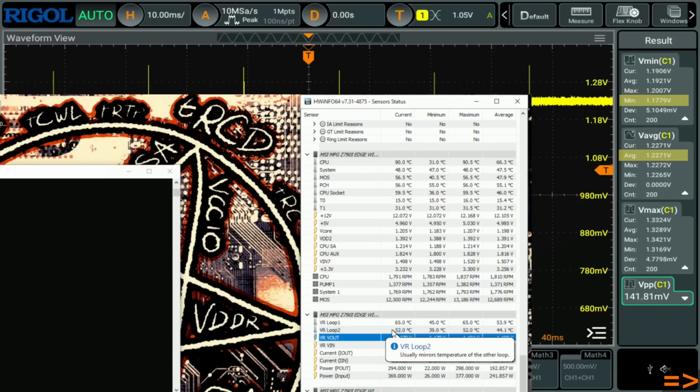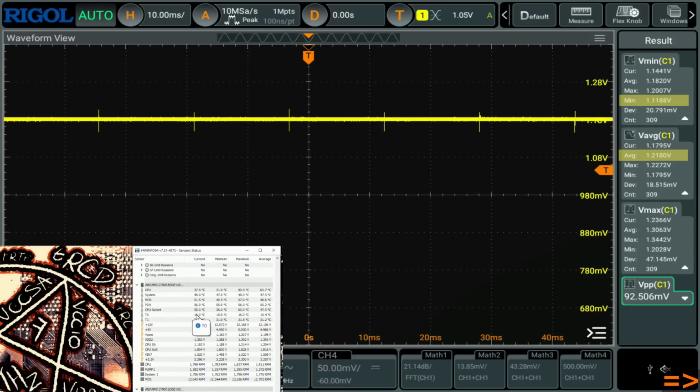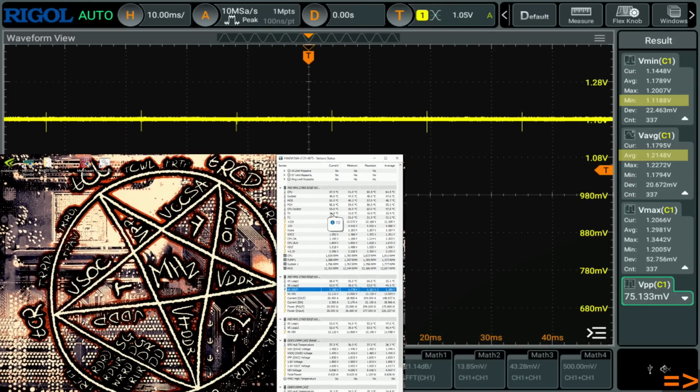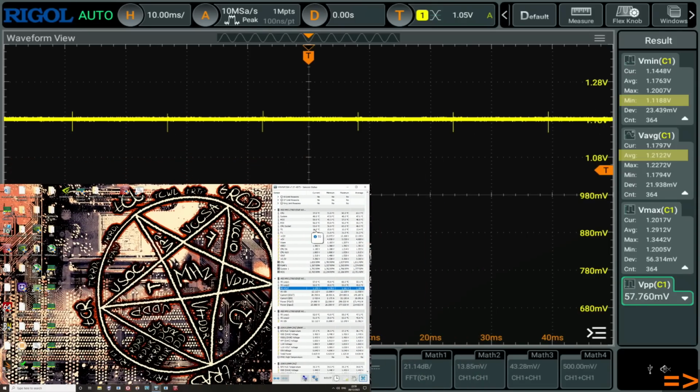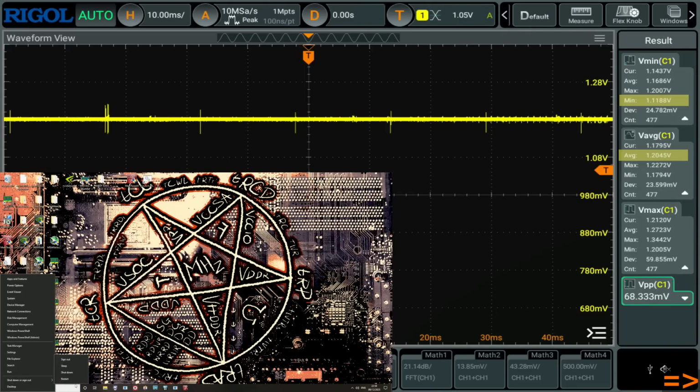Anyway, so in mode 1, we don't have any V-droop. The voltage isn't going up or anything. That's just the CPU socket impedance getting in the way. Which is also part of why voltage regulation is so hard. It's just because you have motherboard power plane impedance, CPU socket impedance, that kind of thing. So anyway, now we're going to restart.